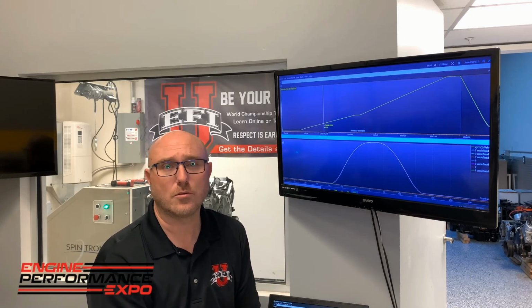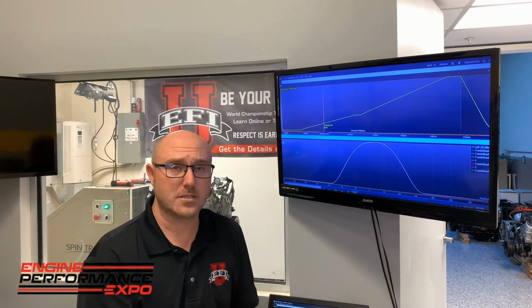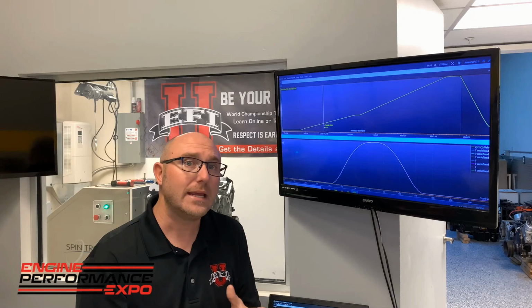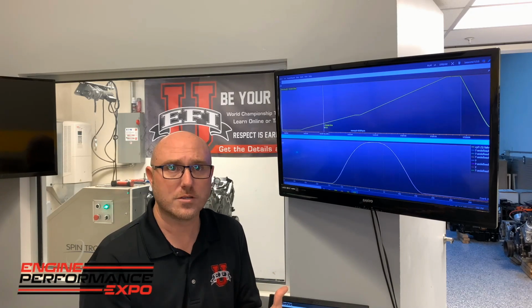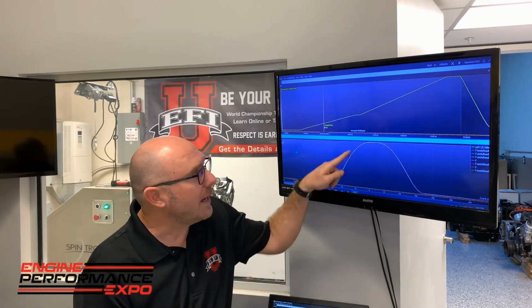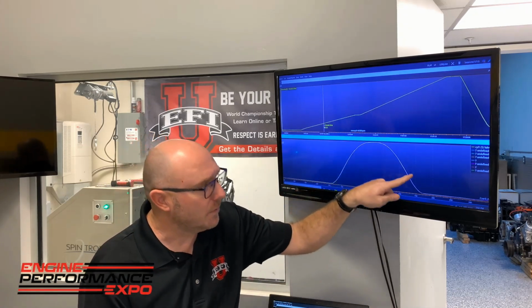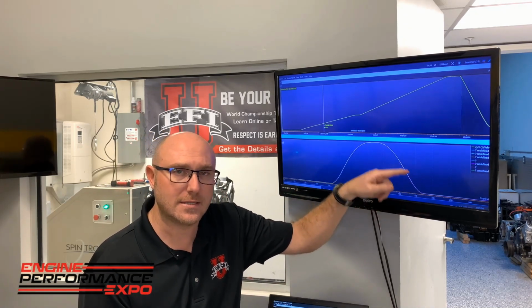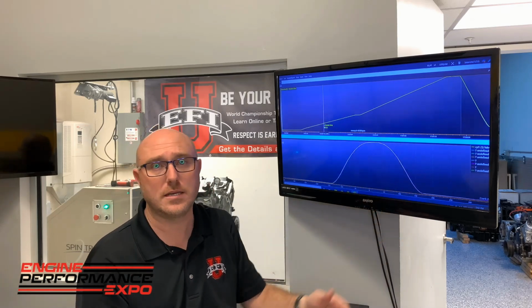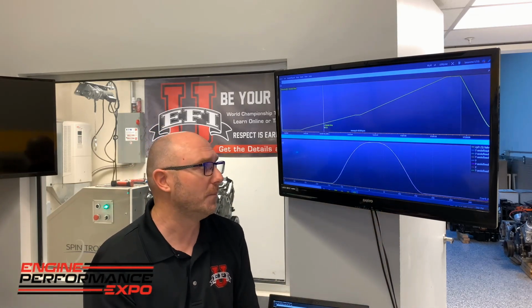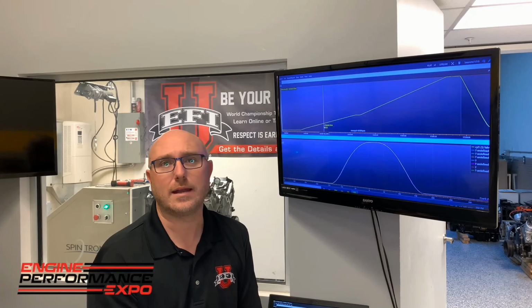Now the problem is when I start running the engine, if, for example, my valve spring can't keep up and doesn't have enough force to hold everything in place, maybe I end up getting more lift over the nose than I want. Or maybe it comes down and doesn't stay on the seat. It hits the seat and comes flying back off the seat, and we call that valve bounce. Well, we would never really know that in the past.